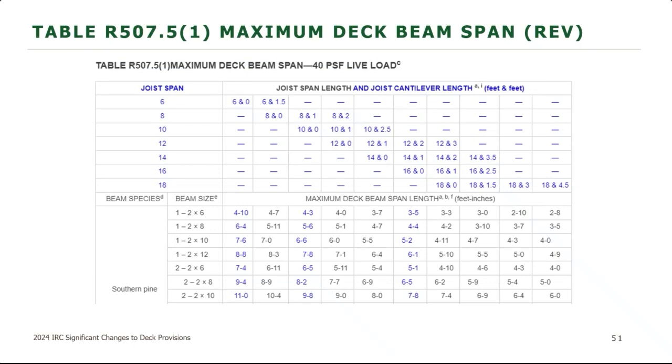on there, and they called it the effective joist span length. So if you're on the 2021 code right now, you've hopefully run into this. So you had the effective joist span length, which took the joist span length that you had and then applied a factor based on how much of the cantilever was out there. So if you had a really short cantilever, you could actually reduce the joist span that you're going into the tables with. If you had that full cantilever, well, then you were coming up with the same numbers that you would have previously. So it was a little bit confusing.